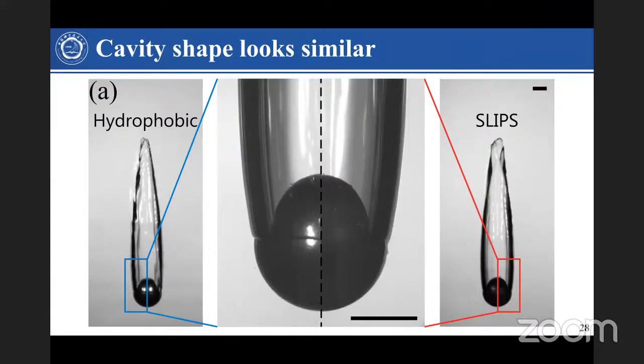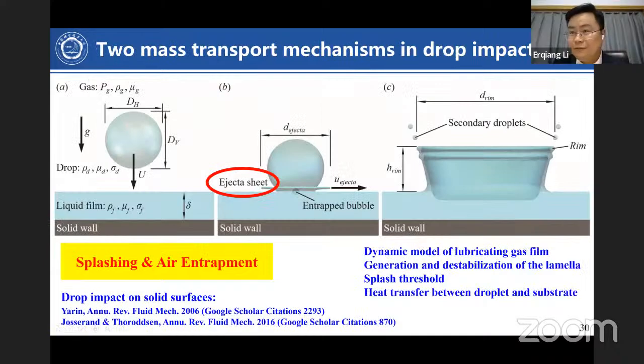Yes. Even if we use actual high-speed imaging, it is not fast enough. Even at 5 million frames per second, it is still not fast enough. It depends on what you want to see. With this kind of high-speed camera, you will see the radius growing versus time, and you will probably get a law like the power of 1/2, which means half. You will think it is not an inertial regime, but that viscosity and inertia are both important.